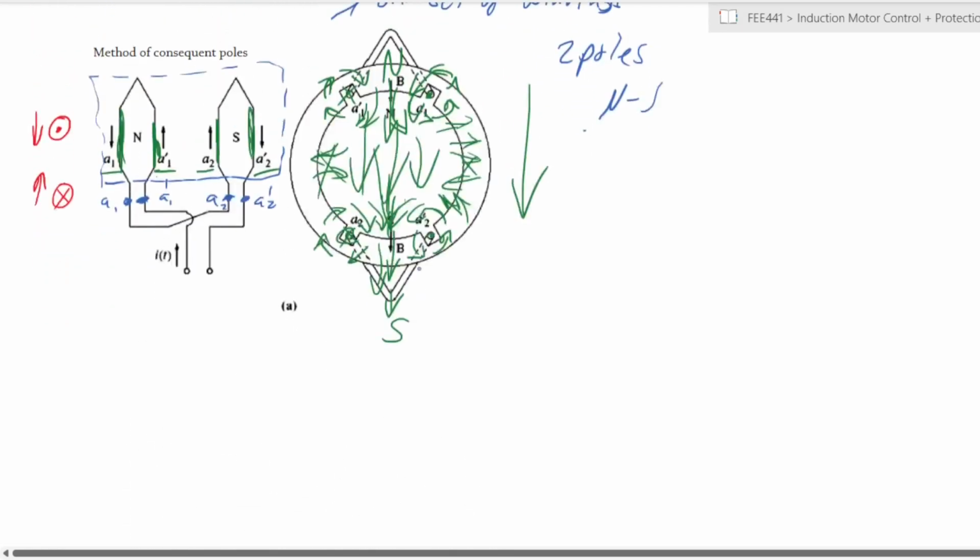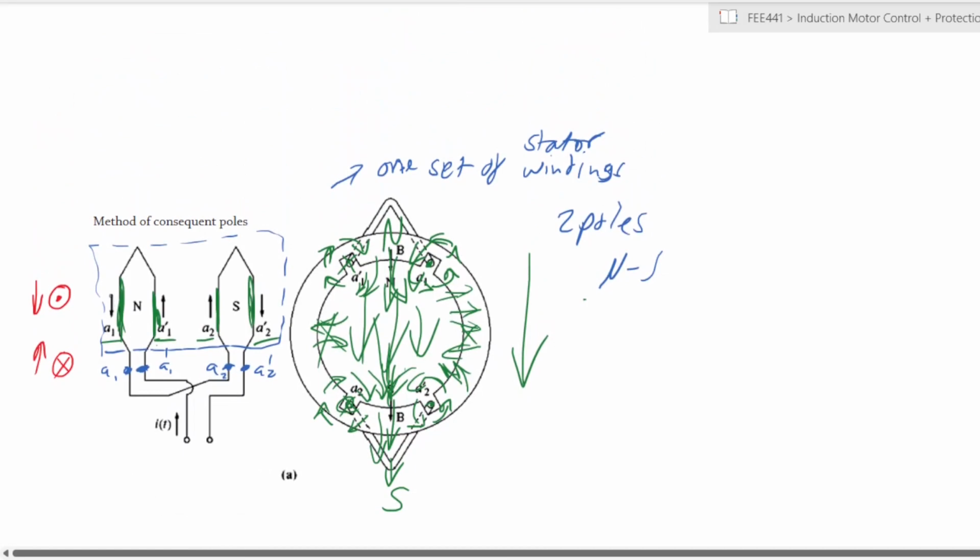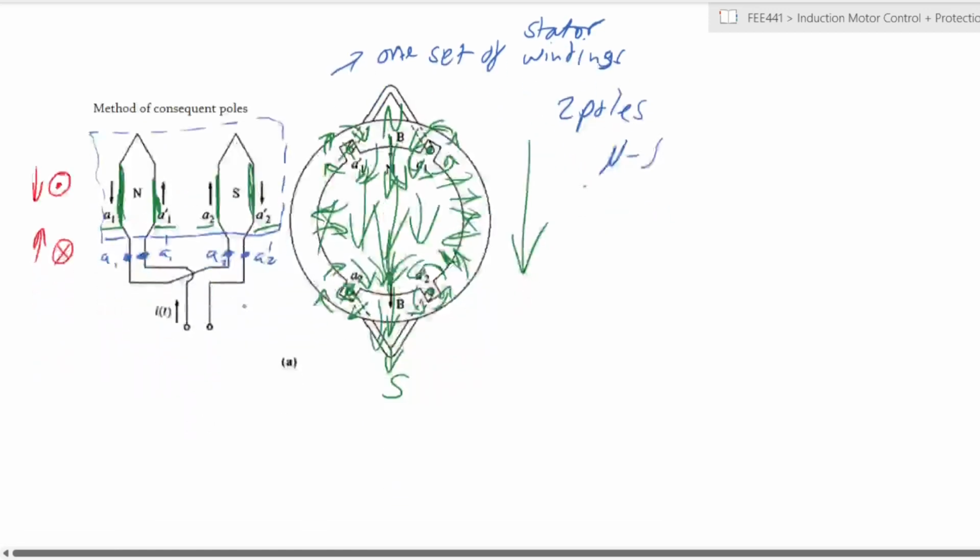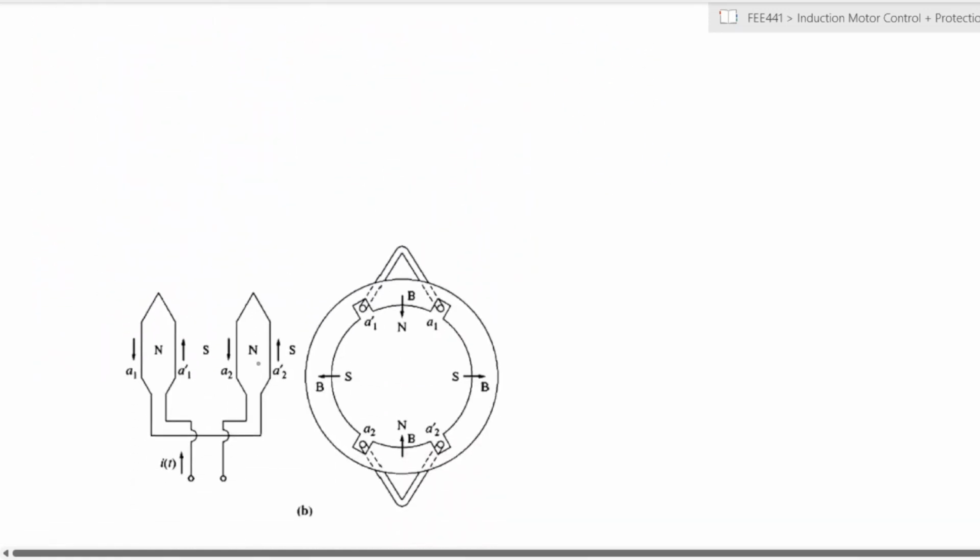So if you see here, current flowing on the A1 side is downward and upward, and the A2 side upward and then downward. But if they were all in the same direction, so down, up, and down, up, the same kind of configuration, if we use this new configuration, we would then end up having the magnetic fields that are here slightly different from what we had before.